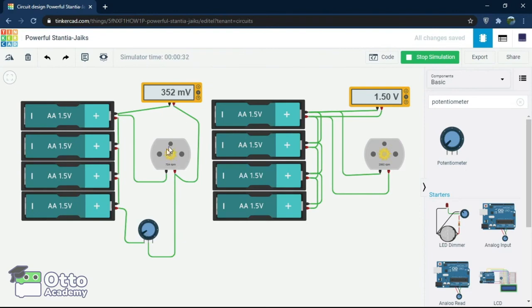With almost 6 volts going, we see the engine moving at 11,000 revolutions. If the batteries start to run out or finish, we can see how this will work by decreasing the resistance of the potentiometer. Thus, we showcase how the batteries look when becoming drained. By moving the potentiometer, you can see that the revolutions are decreasing. When we move it all the way to 0, we are simulating that batteries have been drained and the motor slowing down to a crawl.